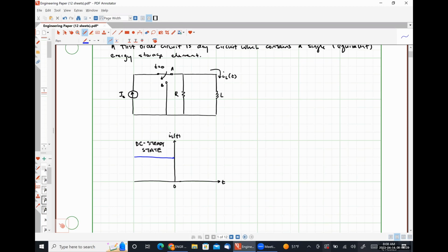So we're not feeding any more energy into that system. What we will see is that the inductor is going to distribute its energy to that resistor, which will convert it into heat over time, because that's literally all a resistor is capable of doing. So we should see that the inductor is transferring its stored energy to the resistor, and as that energy gets converted into heat, the current flowing through the inductor is going to go towards 0.